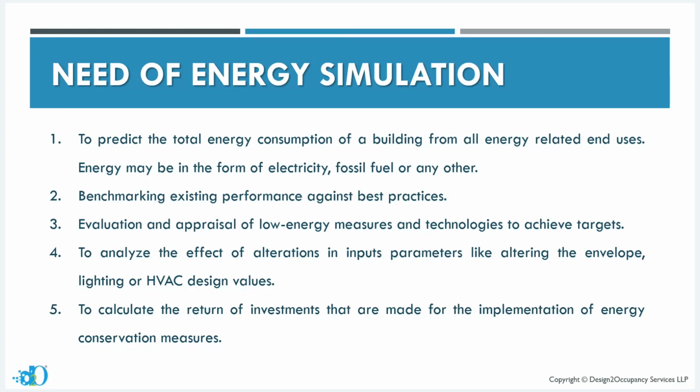We need to know how much consumption is going to HVAC, how much is going to the lighting. So we can predict it, and then we can optimize the system. We can suggest the ECMs, which are energy conservation measures, in which we suggest to the client, okay, you can put that sort of light, that sort of HVAC equipment, and in this way, you can reduce the energy consumption. So this is the one thing.